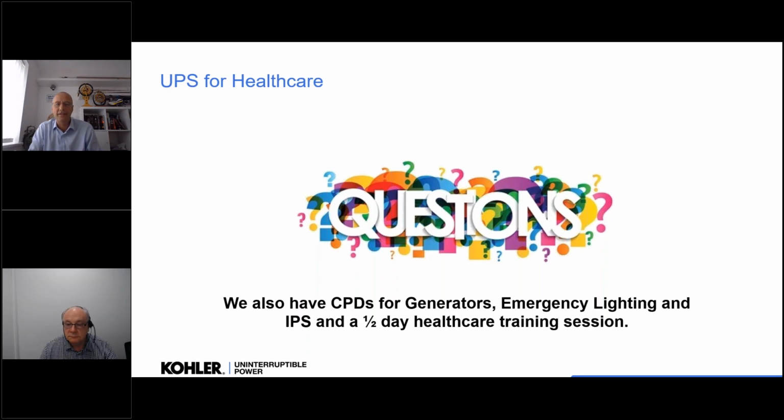So with that ATS, the UPS will remain on mains and have the battery as a backup in case both fail. Everyone has to analyze and risk assess what they have, but we see that the use of an ATS is a very useful way of maintaining the supply to the unit without having to use the battery if not necessary. Thanks, Alex.